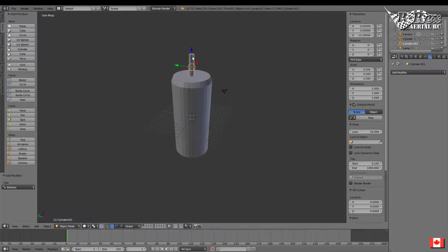The other thing you can always do is, if you know the name of the object, here it's cylinder 001, I want to Boolean, and we can either select it from the list or start typing the actual object name and select it there. Alright, so apply. Okay, now the original object is still going to be there. It was just used to create the mold.